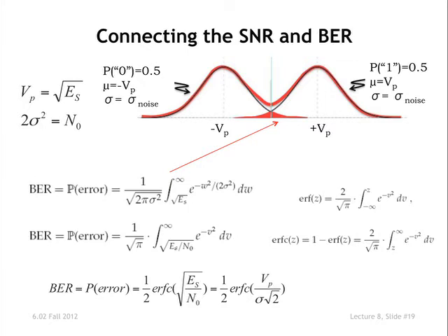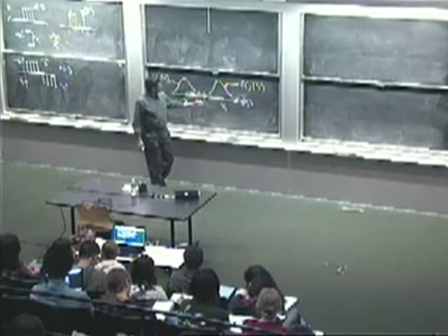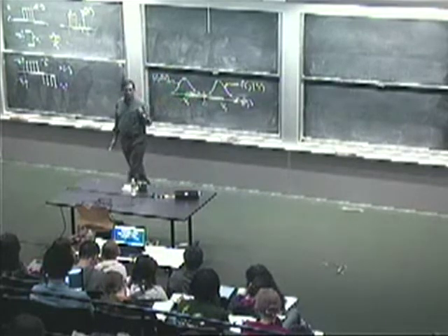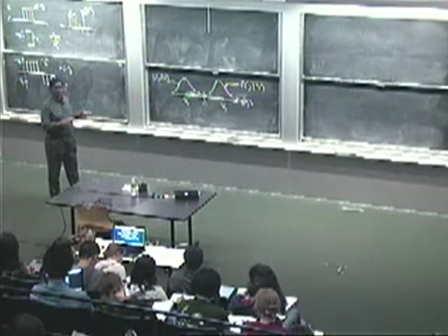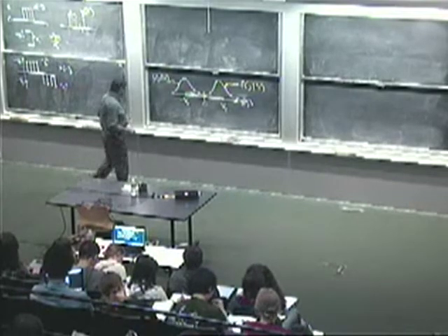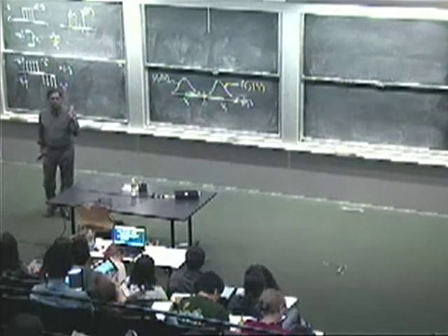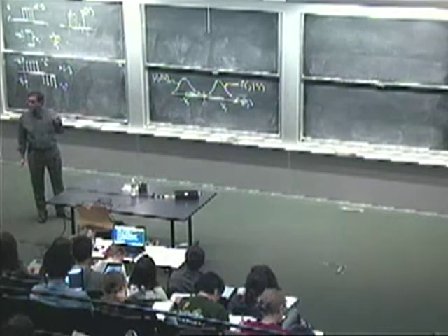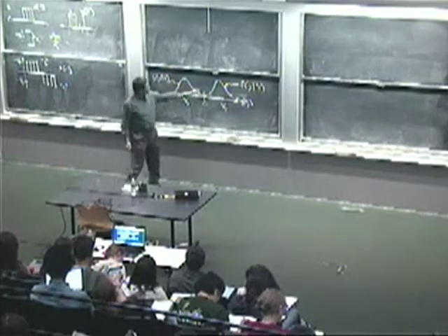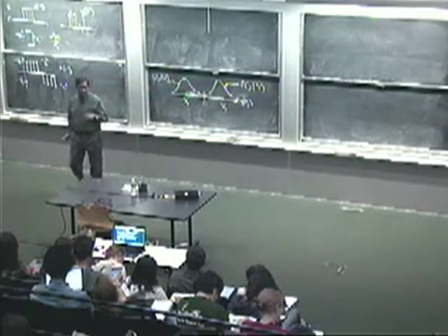Okay? Yeah? Sorry, I have a question about the threshold rule. Is that true when the two Gaussians have different variances? No. Okay, the comment was that this rule of the threshold being the optimum is not necessarily true if the Gaussians have unequal variances. But I'm assuming IID noise. I'm assuming independent, identically distributed noise. So the noise samples are governed by the same Gaussian right through, and then this turns out to be the optimum rule. Yeah, thanks for catching that.